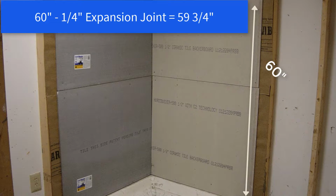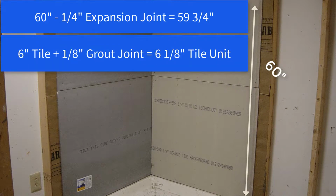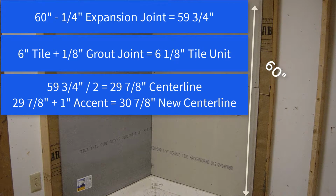The tile area measurement is now 59 3/4 of an inch. Add the 1/8-inch grout joint to the 6-inch tile to determine the tile unit size. Divide 59 3/4 by 2 to find the center line of the wall, which will now be 29 7/8. Add the 1-inch accent difference from the previous cut tile example to the 29 7/8 inch. The new center line is now 30 7/8.